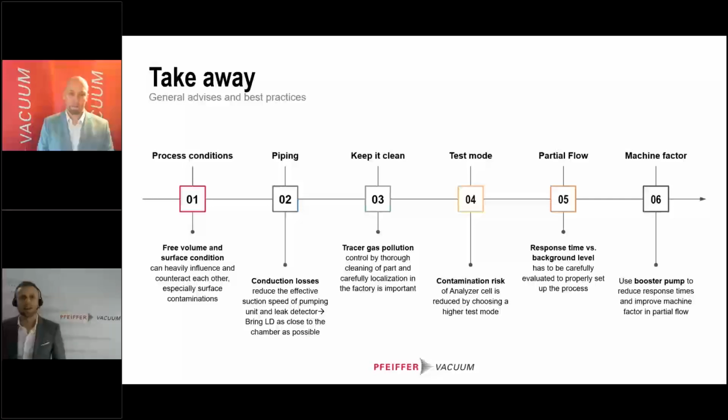Yeah, also the test mode is something that needs to be considered quite importantly, because depending on the test mode that you are working with, you can have an influence on the contamination risk of your analyzer cell. So what we recommend, if it is possible for you to work in the normal test mode with the ASI, then we recommend to go for it. If you are, however, required to go to the high sense mode, then switch to the high sense mode. But the rule of thumb is work with the normal mode wherever possible.